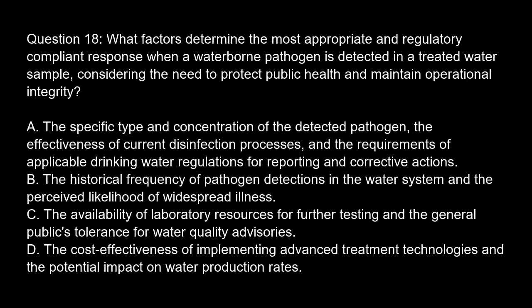Question 18. What factors determine the most appropriate and regulatory compliant response when a waterborne pathogen is detected in a treated water sample, considering the need to protect public health and maintain operational integrity? Option A. The specific type and concentration of the detected pathogen, the effectiveness of current disinfection processes, and the requirements of applicable drinking water regulations for reporting and corrective actions.